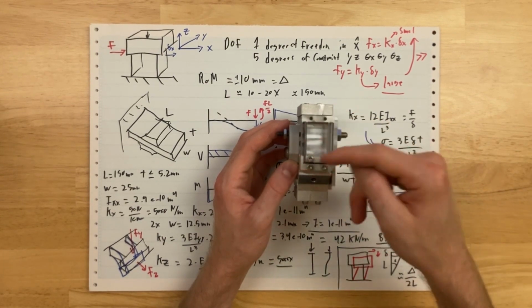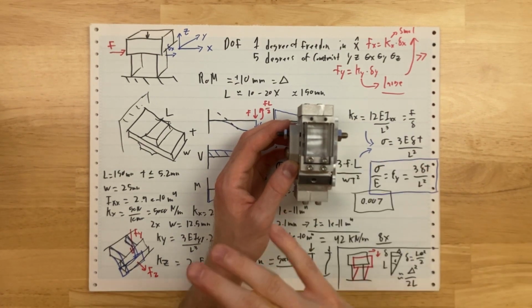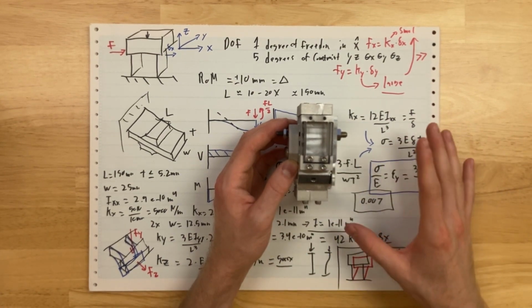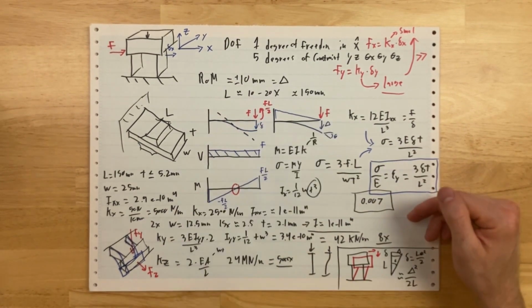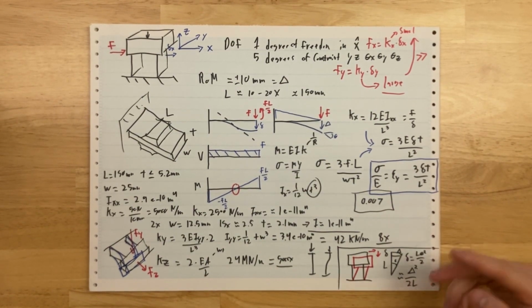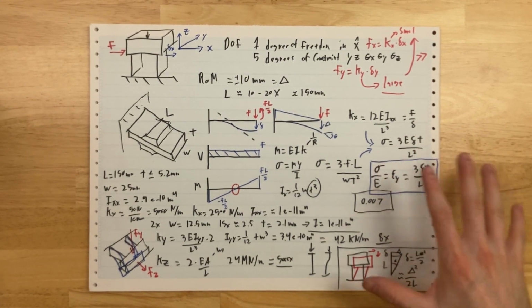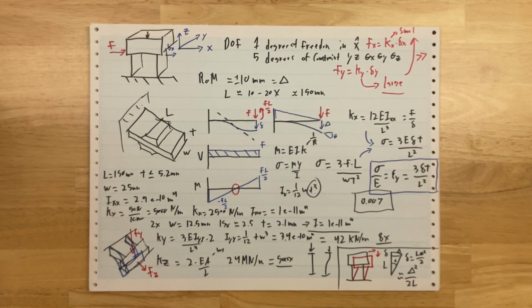Of course, there might be slight defects, slight misalignments, like the thickness of this beam might be slightly different from that one. But essentially, if it was built perfectly, you would have no error. And so you have a lot of these tips and tricks to solve parasitic problems. Eventually, at some point, it becomes less valuable. Like, you end up doing so much work to try to fix some little parasitic problem, you might as well just measure it really well and compensate it in some other way.